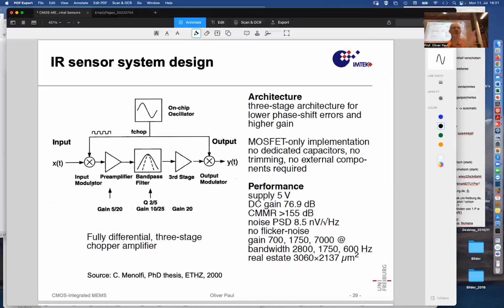I mean, it's there because the lattice vibrates and so on, has a temperature, and the carriers have to follow that temperature. And then there is this cutoff frequency, and then it would be ideal to make all measurements at frequencies above that cutoff, because then you're on the noise floor, the minimum noise that for sure cannot be overcome.